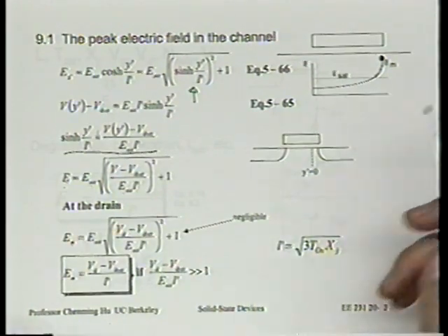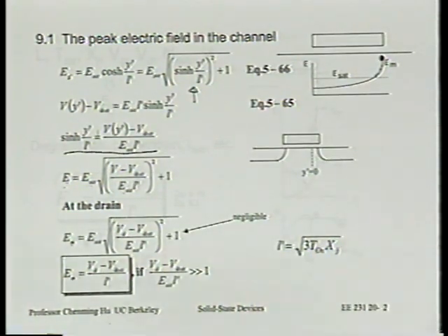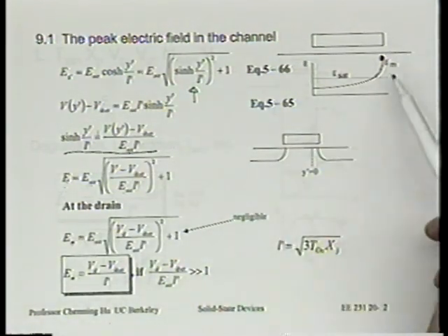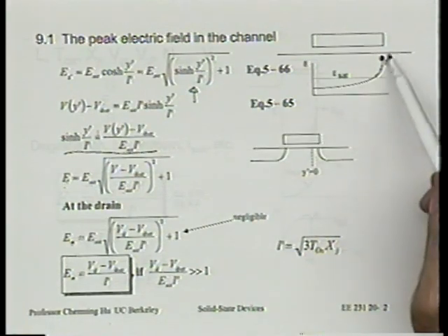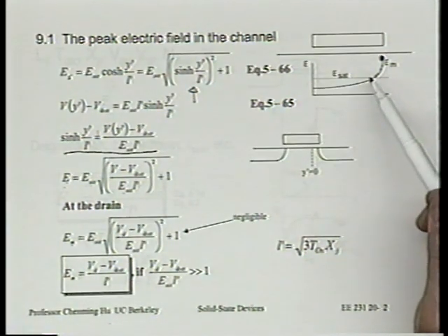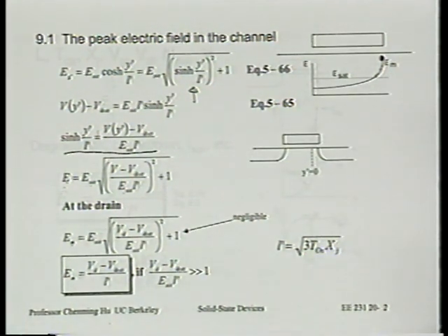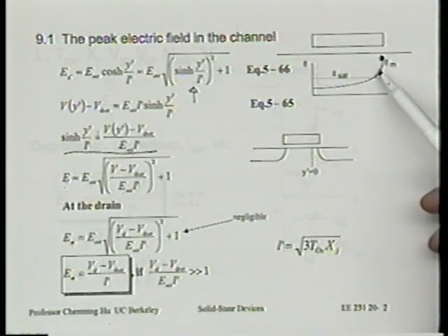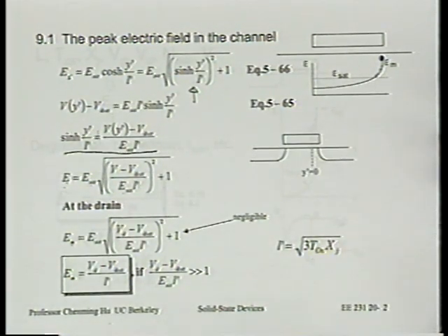The reason is that everything we're going to talk about later on, such as the impact ionization rate, is a very strong function of electric field. So most of the impact ionization is happening really near where the electric field profile peaks, right? Where it's 20% below the peak is really not that important, just because these high field effects are all such strong functions of electric field.